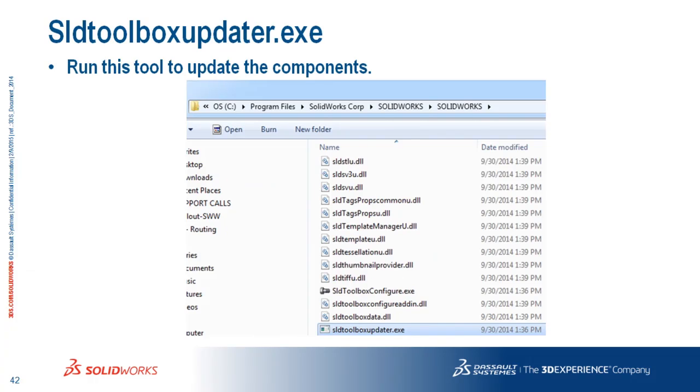Once those are done, SOLIDWORKS pretty much doesn't know anything about your toolbox, okay? It has file locations, but it has no idea what the content is yet, okay? And some of the stuff I've done in the repairs, we've had to rename this stuff just to get it to reload all the data into the toolbox, okay?